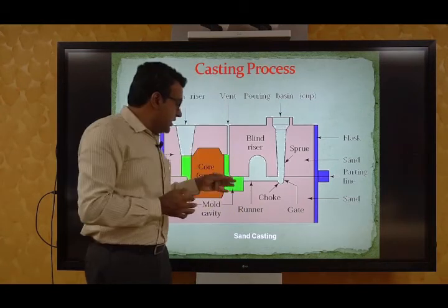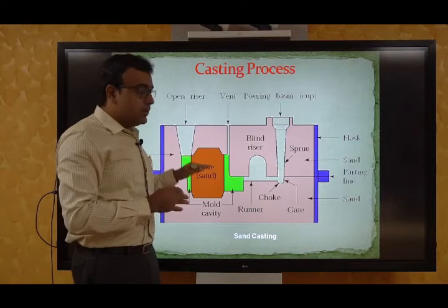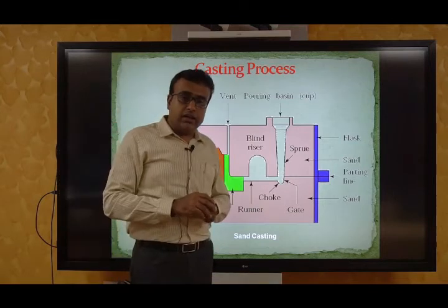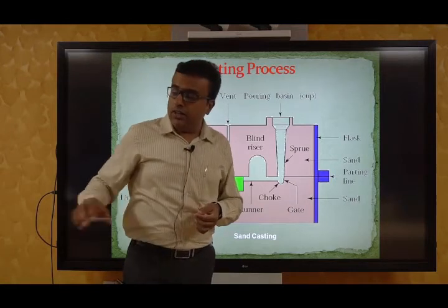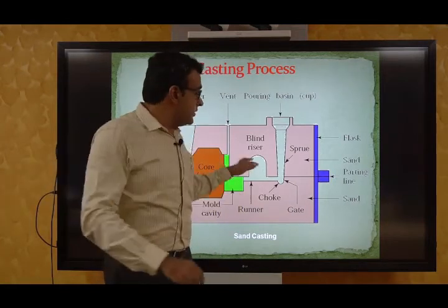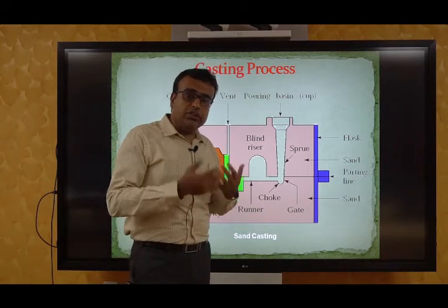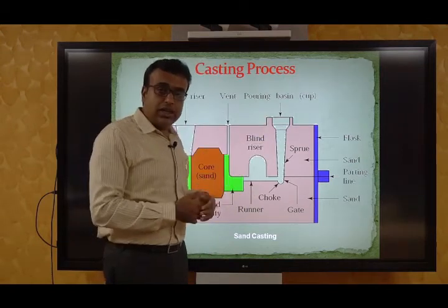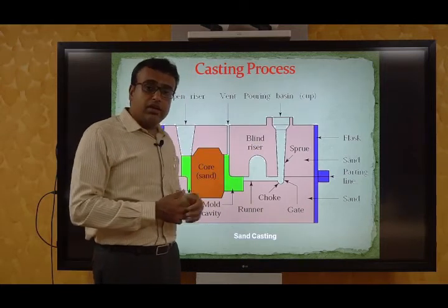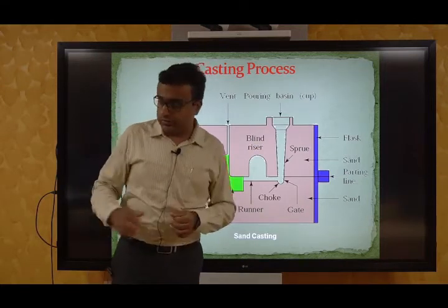Once it is done, we make sure that there are no chambers left to be filled, everything is totally covered and filled up. Once it is filled up, we wait for it to get solidified, and once it is solidified, we break open this, take out all the sand, and we have the product ready, which has to be finished.